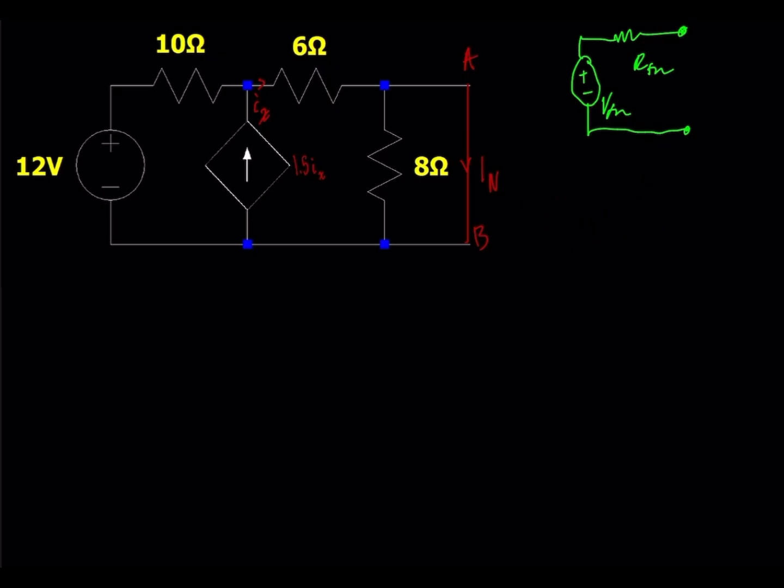When we solve the circuit and find this value, because we have solved for the Thevenin voltage, which we found to be 32 over 3 volts, if we just use Ohm's law and divide that Thevenin voltage by the Norton current, we'll be left with our Thevenin resistance, which is again the resistance seen from those terminals.